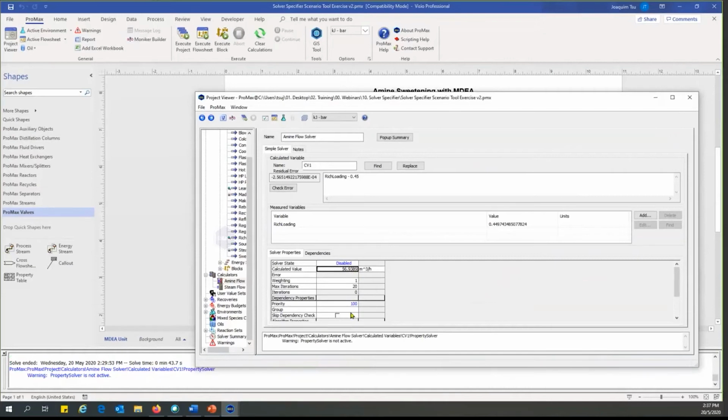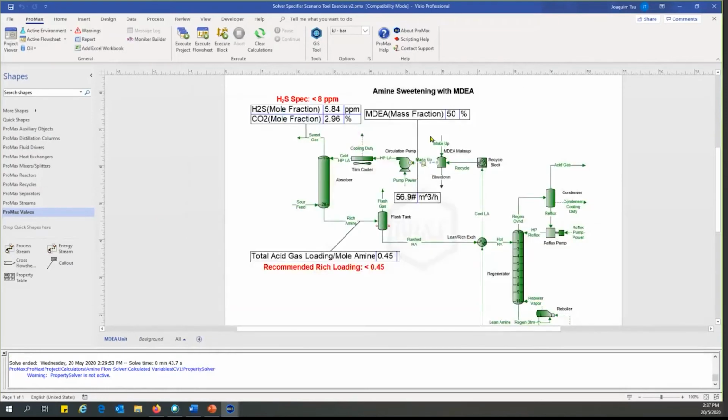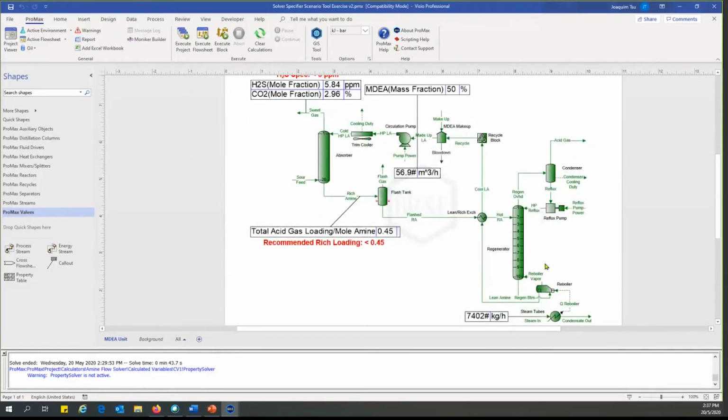You can leave this on if you wanted to study something else, but in our case, it makes more sense to leave it off because we are limited by how much flow we have in our pump, as well as the size of our reboiler, how much steam it can even take. So by disabling it, these two numbers will more or less stay fixed throughout the whole study.